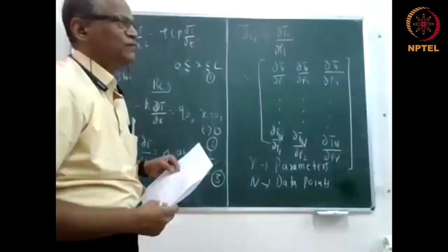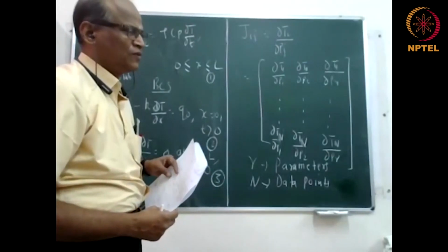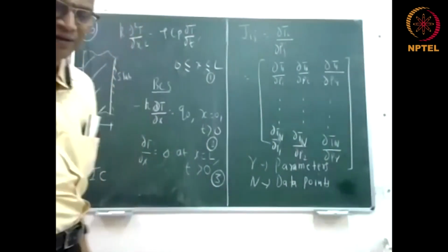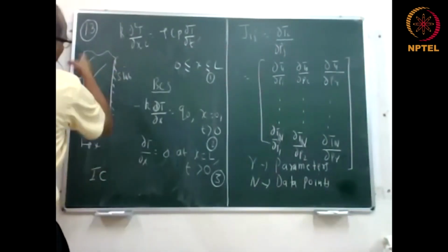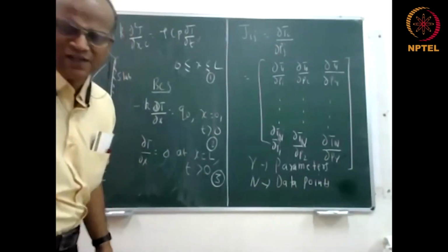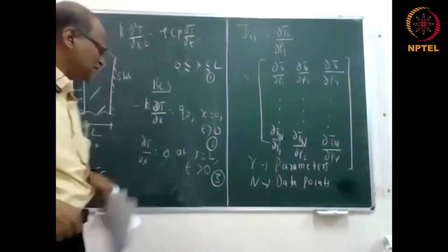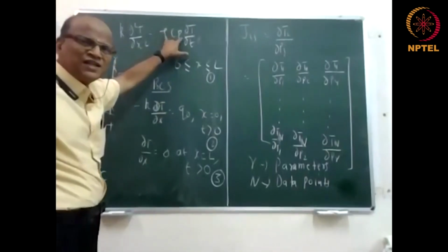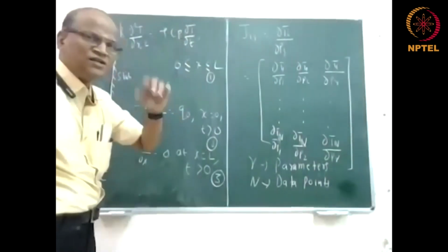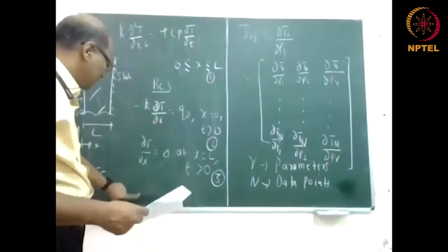The other side of the slab is insulated so as to prevent a steady state from occurring. Exactly. What is the story now? This side is insulated and I'm continuously heating, so the temperature will continuously increase. So there is no steady state solution to the problem. So it is not just the equation which will decide the temperature distribution. Please note it is a boundary condition which can really trouble it.